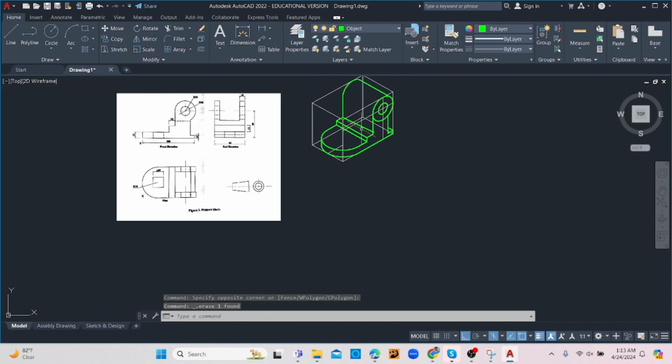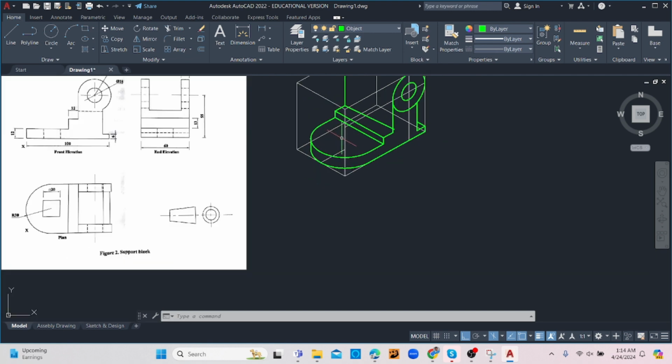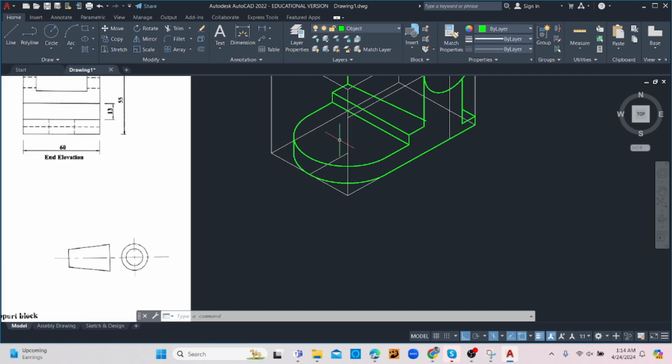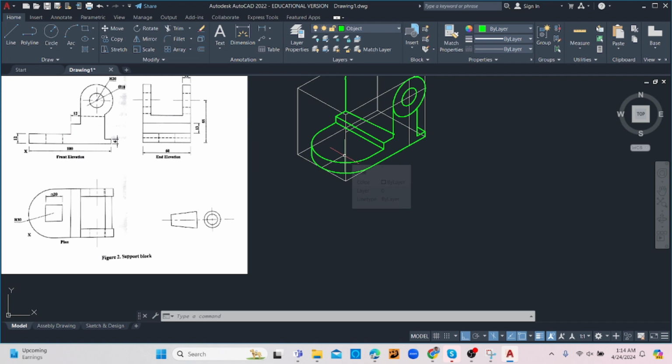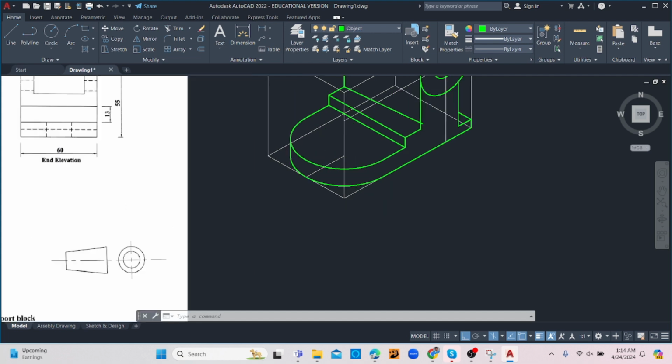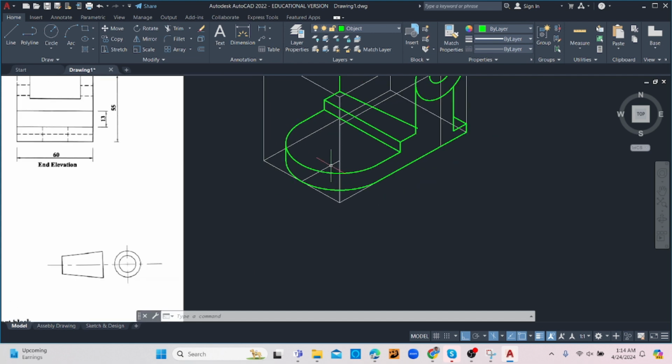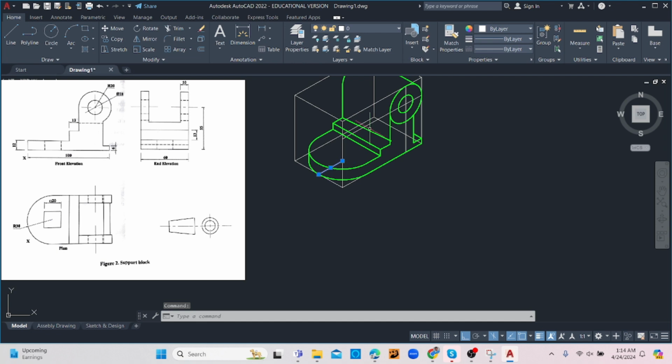The other portion that we need to sort out now is the rectangle here. The rectangle is going to be in the center. So remember, we had drawn this line here. The rectangle, or the square, is going to be 20 by 20. So what are we going to do? You see this line that we have here? Let's just move it up in the air by the thickness of this thing here, which is 12. Or we could copy it. Yeah, let's just move it because we have no further use for it down there. So we're moving it up in the air by 12.